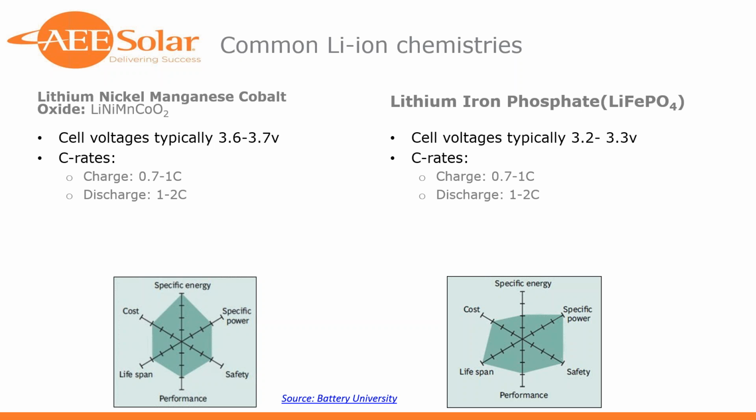Without those communications, you're placing bets on an inverter being able to make really precise calculations on voltage. And unlike lead acid chemistries, where the voltage will sag under load or will rise under charge, the voltage on lithium ion, both chemistries, is relatively stable. So you're talking about fractions of a volt between fully charged and almost all the way discharged. And most power electronics are not sensitive enough to be able to make decisions off of those small fluctuations in voltage. So takeaway here: make sure you've got a provider you can trust.